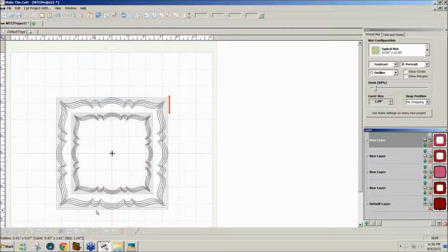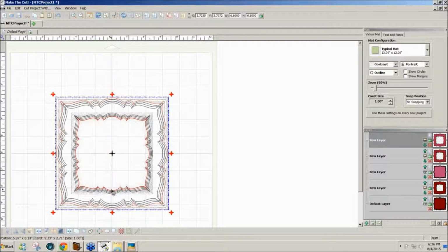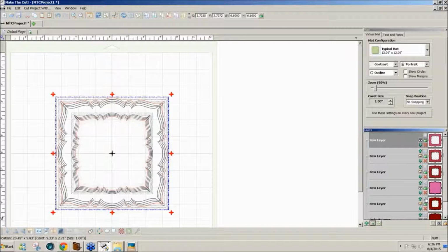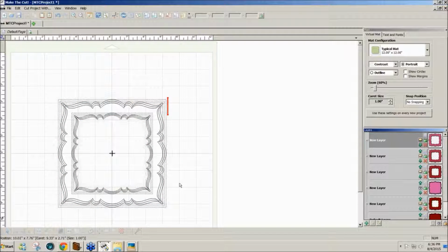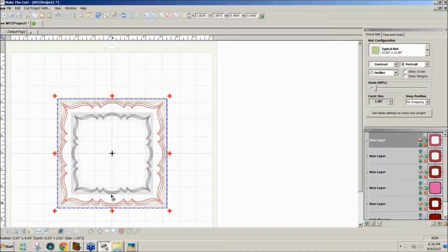So outside, inside, join, own layer, and hide. You'll be really good at this after you do it a few times. Outside, hold shift, inside, join, smaller of the two green plus icons sends it to its own layer, and clicking on the eyeball of that layer hides it.